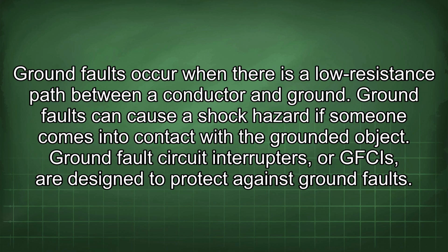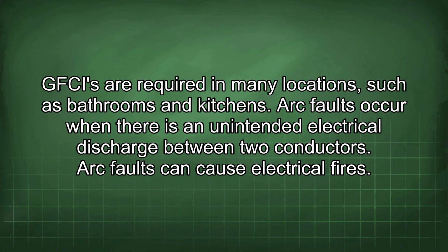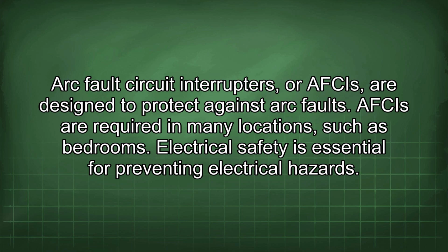Ground fault circuit interrupters, or GFCIs, are designed to protect against ground faults. GFCIs are required in many locations, such as bathrooms and kitchens. Arc faults occur when there is an unintended electrical discharge between two conductors. Arc faults can cause electrical fires. Arc fault circuit interrupters, or AFCIs, are designed to protect against arc faults. AFCIs are required in many locations, such as bedrooms.